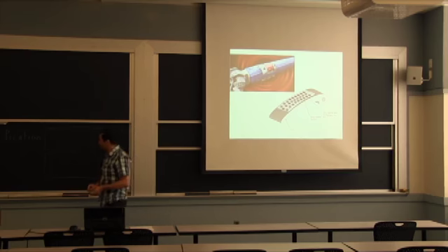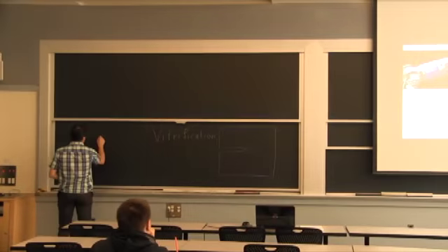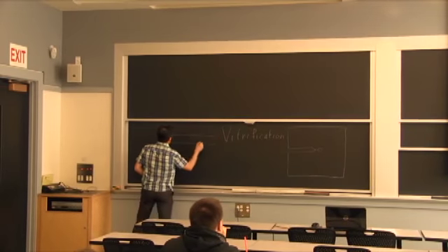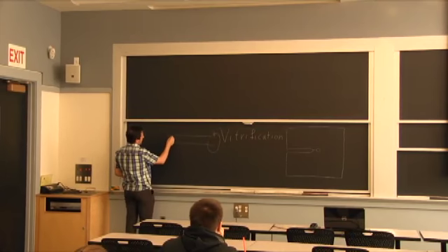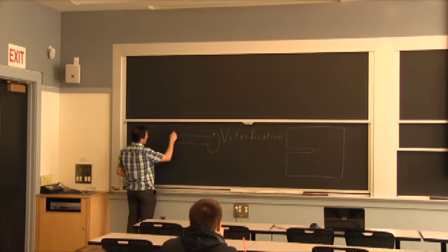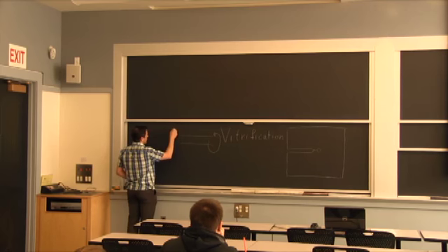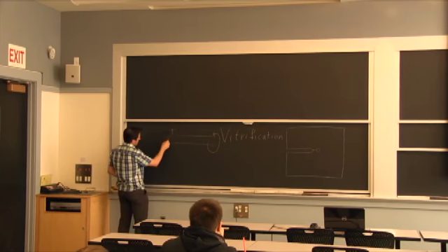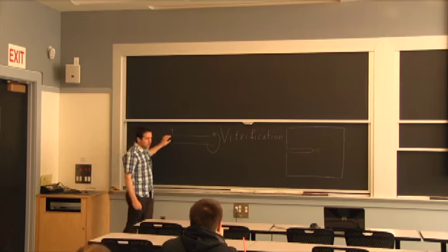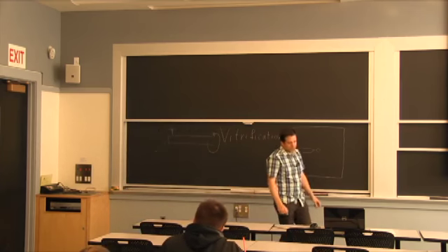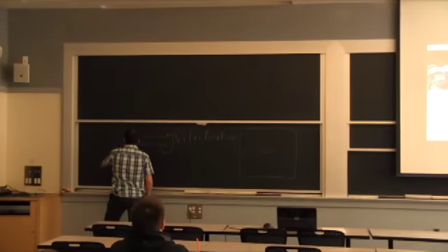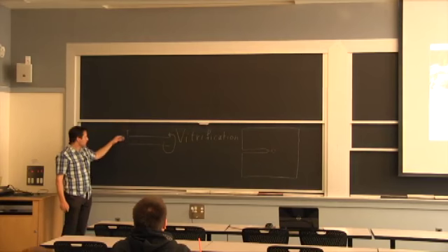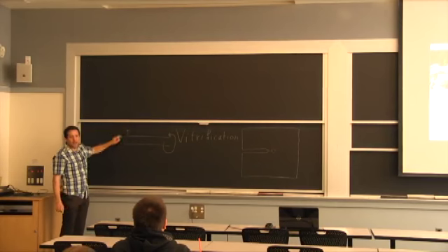What these do as the whole assembly is rotating, it's pushing against the well bore to orient. So you can essentially say, if I'm right here, the whole thing is rotating. And at the very end, when the pad is on this side, I want the pad to push against the formation, and that would be driving the bit this way eventually. So there's a special pulsation kit that is essentially adjusted to your rotation frequency. So each time the pad comes on this side, it gets pushed out, and it's wearing against the formation.